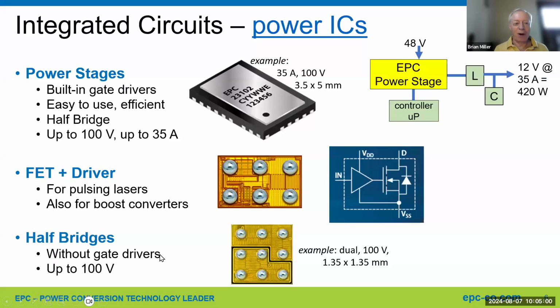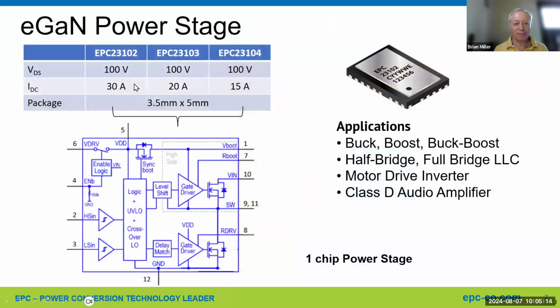But more lately, if you look at the top of the power stage, which has the gate driver built in, that seems more attractive than just a half bridge without. So in the future, you'll probably see more of the power stages being released as a focus. Here's a bit of what's inside. I won't go into details, but just everything: level shifter, a dual gate driver, three different models here, plus another one with an external bottom FET. But if you're interested, it might be interesting to go to EPC's website and type in one of these part numbers to see.